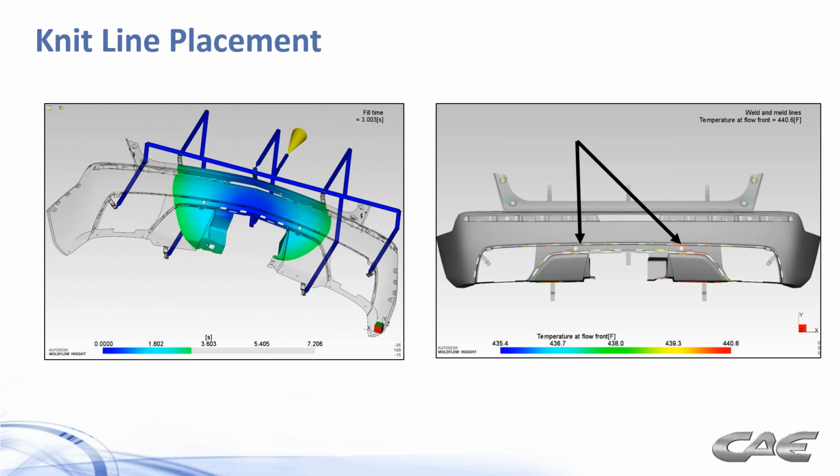But in 3D technology, we can actually put vents in there and define the size of the vent and see how it affects the filling pattern. But we haven't had real good success with correlating that. It can sometimes affect the filling pattern, and it can be simulated, but in my opinion, it's a little iffy at this point.